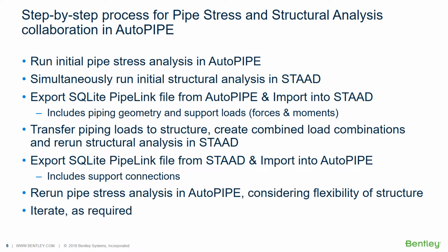And then when you rerun your analysis in STAAD on your structure, I guarantee you will probably see some differences in the stresses in your structure. Of course, with that step, this also means that if you see some stress changes and now you're overstressed, or you have a situation going on the structural side, then you have to actually do something about that. So the structural engineer would want to work their magic, make some changes, add some bracing, whatever they have to do to bring those stresses down, and again, to satisfy the criteria on the structural side.